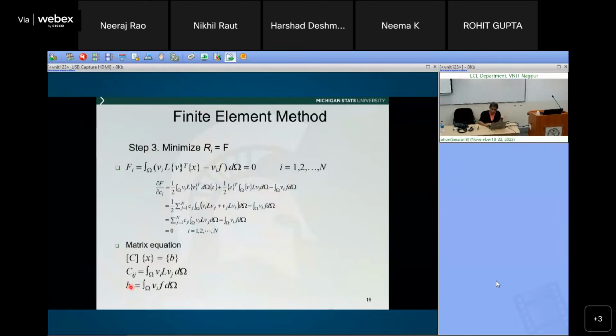So in the frequency domain, all this modeling is only for a single frequency. But when you use multiple frequencies, you have to keep in mind that at higher frequencies the skin depth is smaller, so my discretization has to be finer. Those are the kind of precautions you have to take. But doing everything in the frequency domain is much easier than doing the time domain. Things like that. Yeah, right. Good.